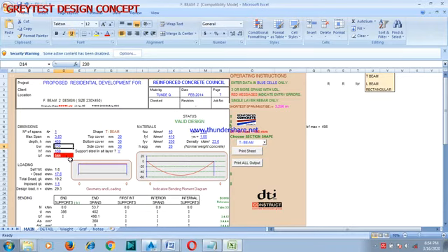Okay, that 544 is not the BF. The breadth of flange is not 544, so we have to change it. Although it has designed it already, we don't need to do this calculation manually, just like the way we did in RCD 2000. Your HF is 150. Here now it has designed it. Look at BF 498. So we'll change this to 498. Okay, click. You see it's no longer showing you red.